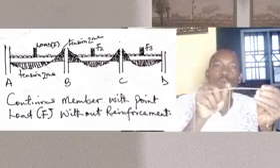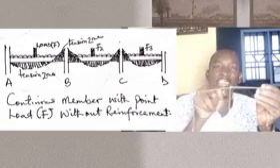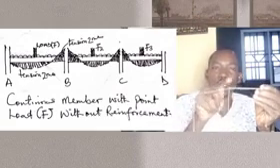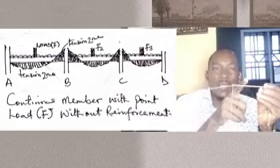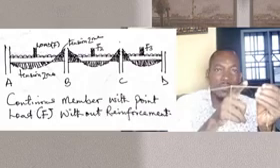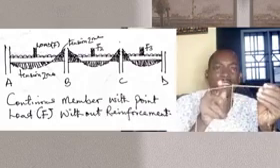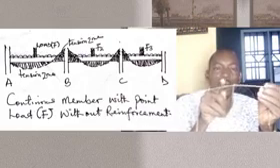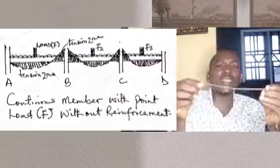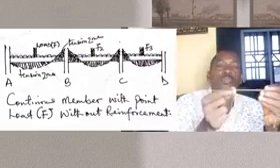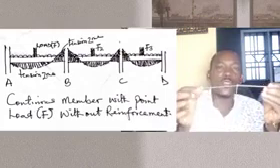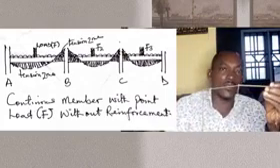Then at this point here, you are going to have tensile stresses developing at the top, at a particular distance from this beam to this other beam. You are going to have a tensile stress developing in this area because of the support condition. So that's the way you are going to have it at this pillar, at this pillar, and the next one.